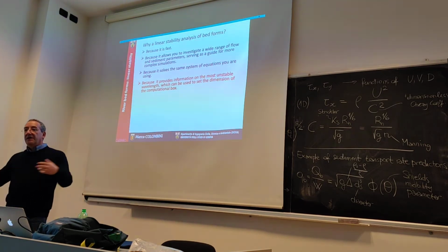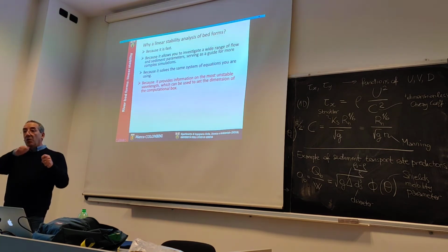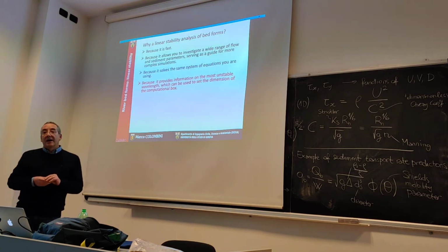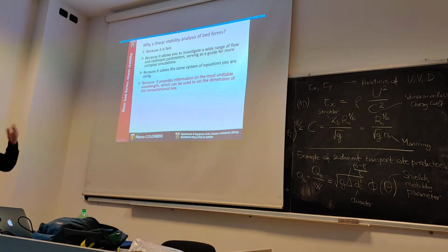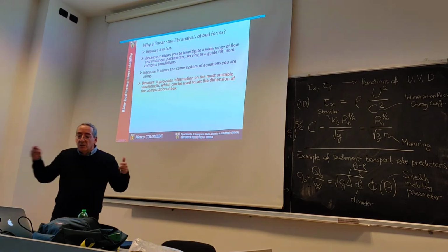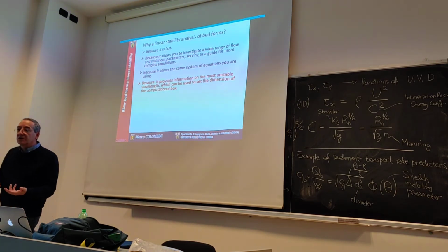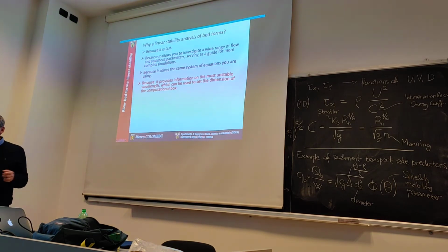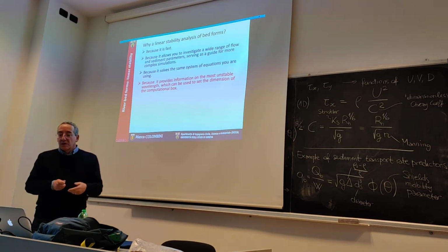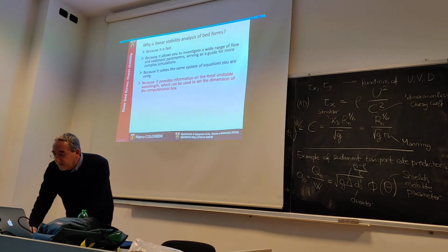So you want the computational box in which you solve the equation big enough to contain at least 2 or 3 wavelengths of your pattern, of your perturbation. And since you cannot adjust the box when you are doing a simulation, you start from some box and see what happened inside, then having information on how long should be the background that you should observe, it's really valuable for people doing numerical.